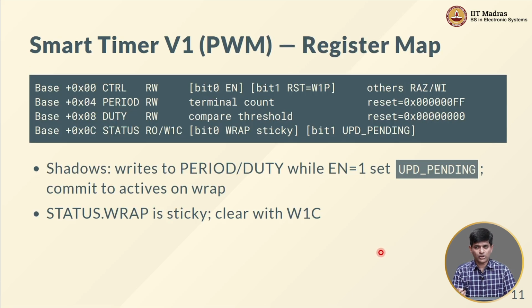So with all of this in mind, we now go and construct a register map. What we say is we have to choose some kind of base address. What is that base address going to be? Well, unlike the case of the ARM UART, which had a 12-bit address space or 4096 addresses, we are going to make do with just an 8-bit address space, 256 addresses.